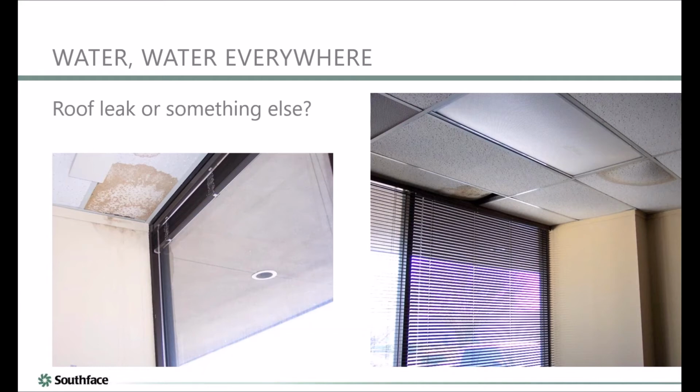Well, I would suspect, since you look through the glass window and there's this downlight outside, yeah, right? A hole. Yeah, there's a hole basically, and so negative pressure is pulling in hot, humid outside air. Yeah. It hit something cold and possibly metallic, like a pipe. Sprinkler pipe, anything. Who knows? But it's hitting this cold duct. Yeah, it's hitting this cold metallic object, and it's raining condensation.